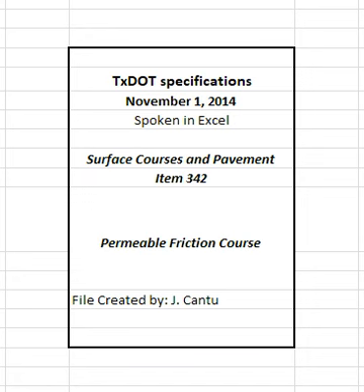The engineer may suspend production if the contractor fails to produce and provide haul tickets and yield calculations by the end of paving operations for each day. Prepare the surface by removing raised pavement markers and objectionable materials such as moisture, dirt, sand, leaves, and other loose impediments from the surface before placing mixture. Remove vegetation from pavement edges.